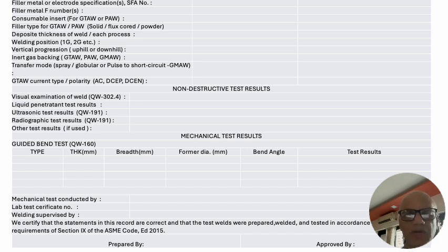In the butt joint we should write down the number of passes, number of layers, and then the guided bend test. For a welder qualification we don't do the tensile, but the guided bend test gives a very fine check of sidewall fusion which can be missed out in ultrasound or in X-ray radiography, but you will get it if the bend test is correctly conducted.